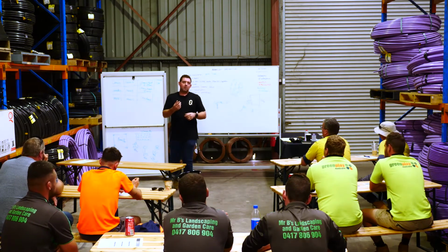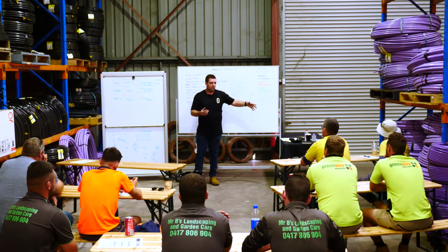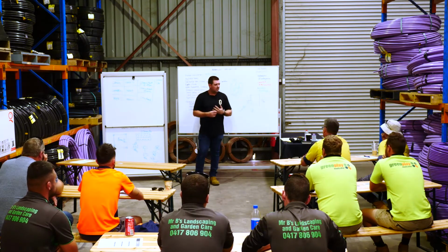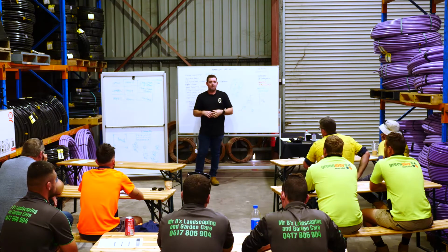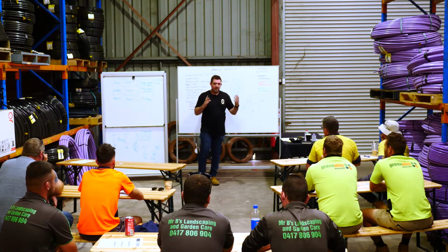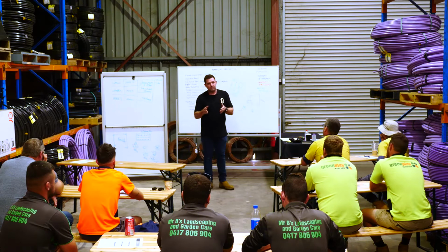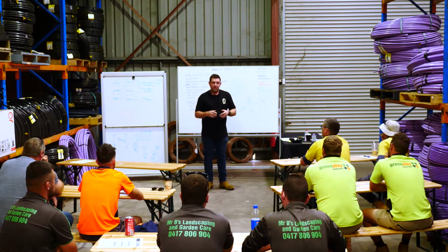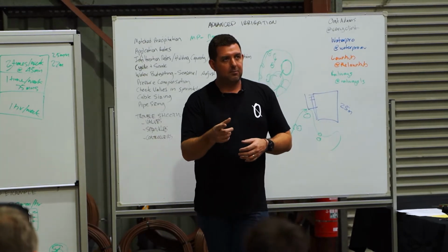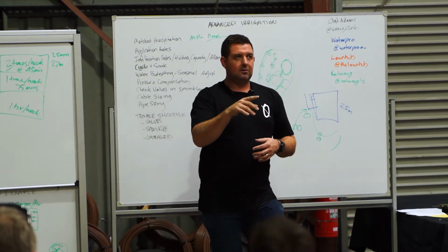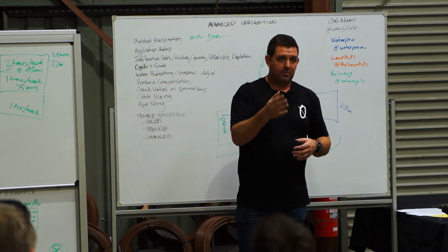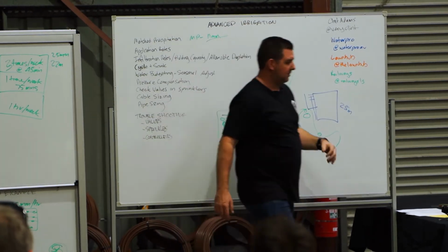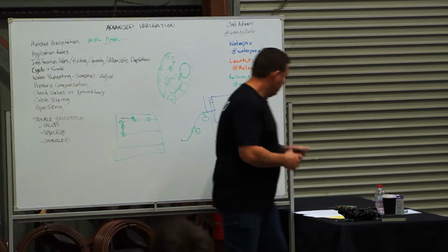So the MP rotator was the original matched precipitation nozzle. It was owned by Nelson, I think, or Walla Walla, and they sold it to Hunter, and then Hunter took it and ran with it and made it a global thing. Rain Bird played catch-up against that for a decade or more and came out with the R-Van, which is the same concept. It's a finger spray. It's a slightly higher precipitation. So like I said, it's 11 for the MP, and then the R-Van's somewhere around 14 or 16.